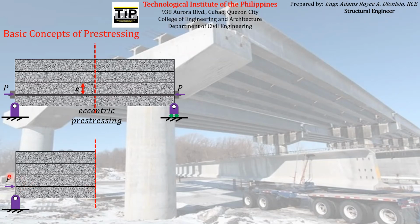And that particular force that will counterbalance this must be located along the line of action of this force so that it will balance this force with the same magnitude but opposite in direction. So let us just call that internal force that will counter this external force when we cut the beam, P also. So again, move P. I just move this force from this location to that location to have an open space here, a free space here, so that the line of action of that internal force acting on this cross-sectional area coincides with the line of action of this external force, the compressive force coming from the pre-stressing reinforcement, so that they will balance each other. So they have same magnitude but opposite in direction and same line of action.